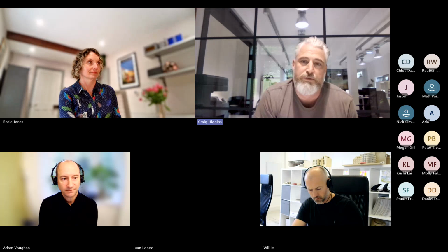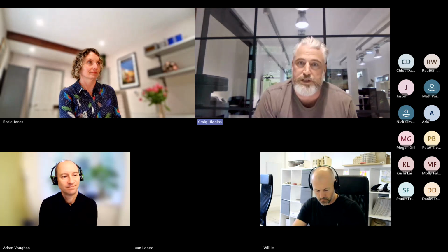There's a lot of tinkering around the sides, but the reality of it is any single person on this call, the way you can influence your impact on the world is just good design. And by good design, I don't mean having something which is really brilliant now. It needs to last. And then when it doesn't last, you can take it down. So there's a lot of emphasis on composite construction. You'll tie a steel beam to a concrete slab to reduce the weight of the steel beam. And that is brilliant if that structure is going to remain forever. You've reduced the initial embodied carbon that you've used, but you then can't reuse that steel beam because you can't deconstruct it in the future.